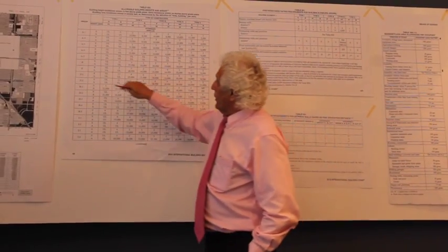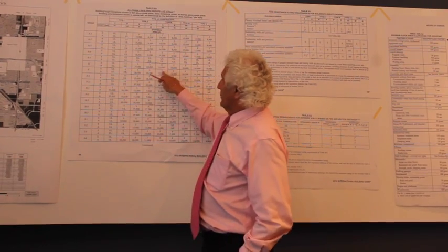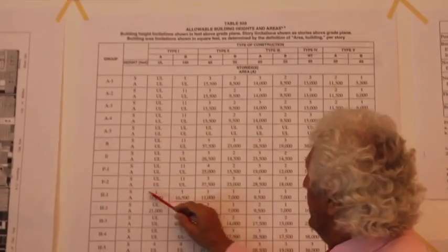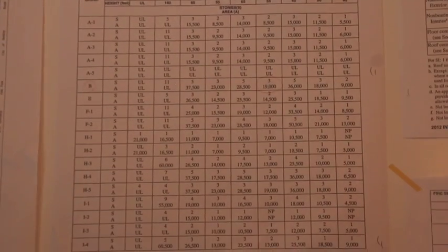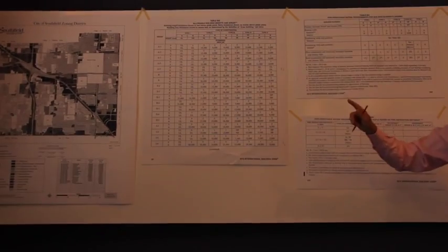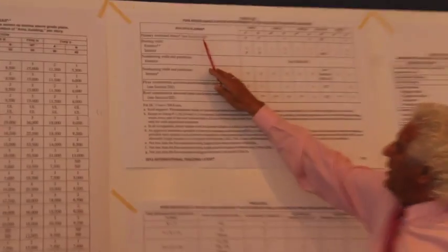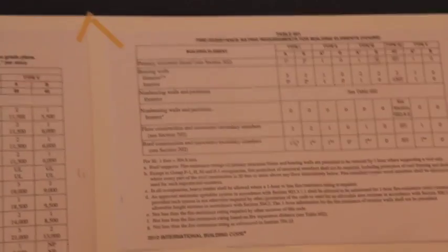So then you need to see, what is your construction going to be? So if you want to build a hospital, then you're going to have to look at something that is in a type 1 or type B construction. And once you establish that, then you work with here, this is table 601. And these are the basic structural elements of a building.